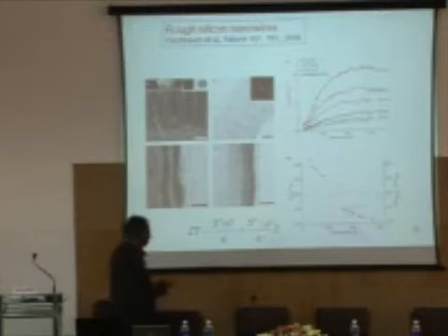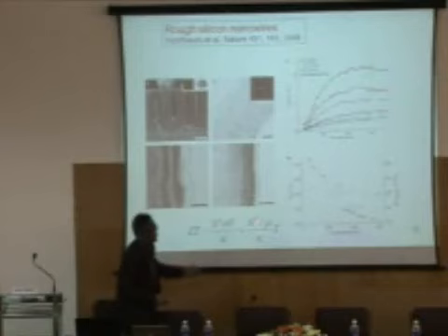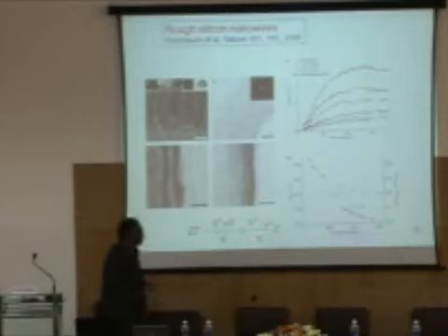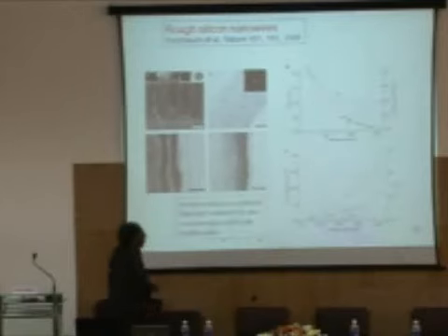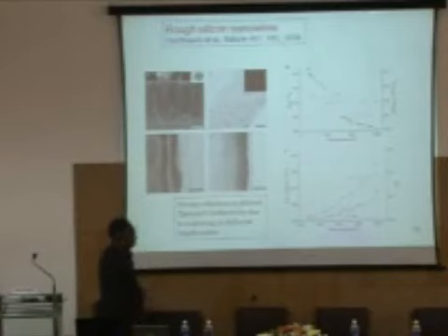Bulk silicon is beautiful, has long mean-free path and good transport. And so what happens here, this S squared, the numerator here, is reduced by a factor of 10. So you gain through this, you lose through that, so the net upshot is about 0.5. So again, you have gone from the 0.1, 0.01, 0.05 range to a fat 0.5.